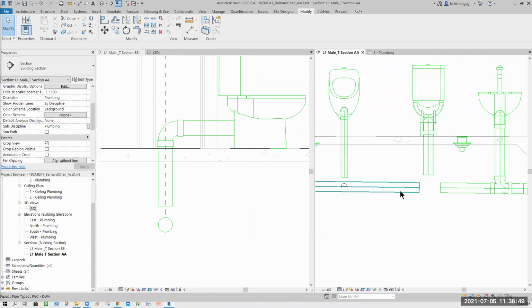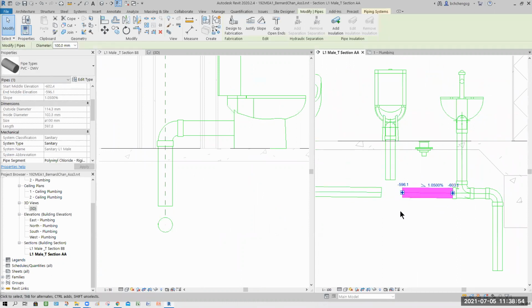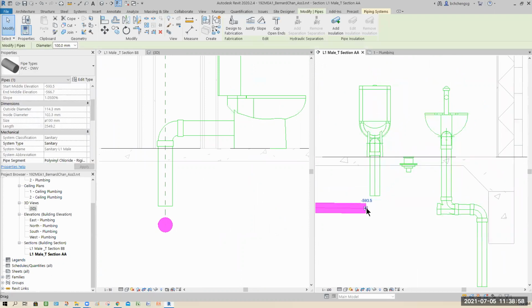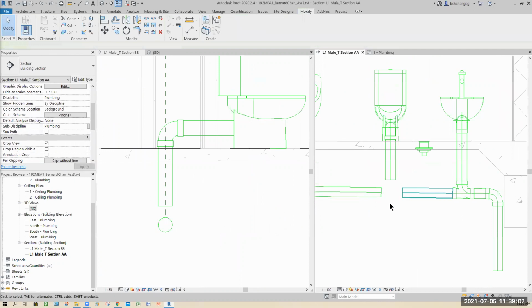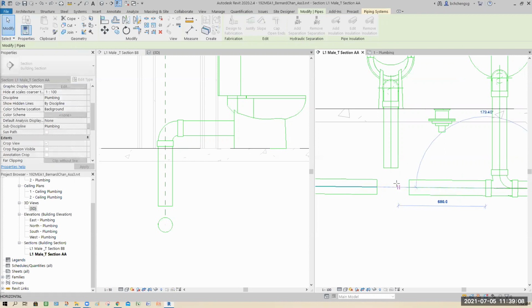You need to connect them first. So how to connect? Shortest, delete away. If I'm going to connect this to here, hold on, let me see. Can I connect the two pipes? If can, they will auto link up. But you've got to observe a few things. Drag. See this: parallel and nearest. At least two O snaps appear.